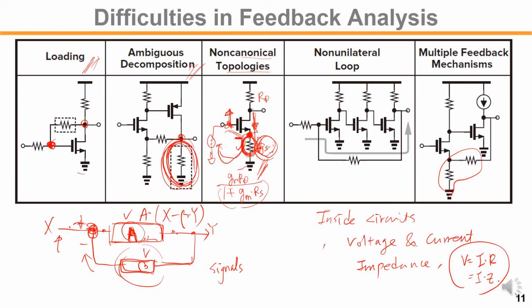For non-zero RS, the amount of voltage variation on the source will be reduced by the negative feedback, right? I mean the amount of voltage difference in VGS. So VGS will be affected by the RS. If RS becomes infinity, then the small signal variation of VGS will be small.